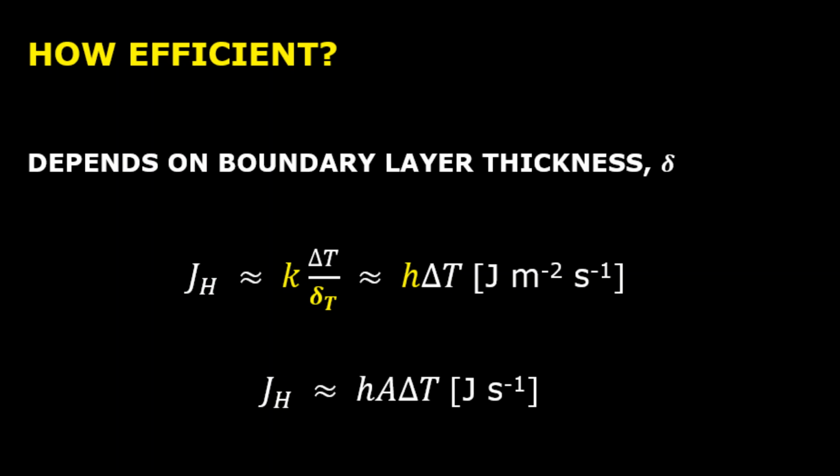And obviously, the thicker the concentration boundary layer is, the higher mass transfer resistance, and therefore the lower or the poorer mass flux you will have. If you can compute the thickness of this concentration boundary layer, then you will likewise be able to estimate both the local and global mass fluxes. So exactly the same logic applies to mass transport.